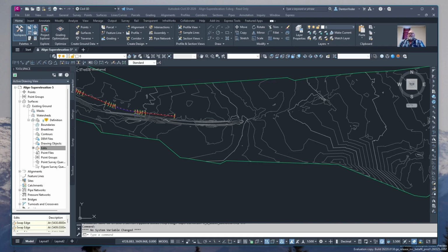In today's lab, what we're going to do is do a 3D print of a stream channel that we want. So first off, I'm going to find a drawing that has a surface that I want to use a copy of. And the process I'm going to do is quite destructive to the drawing. So I'm going to W-block out the surface I want to use into a separate file and then use that.